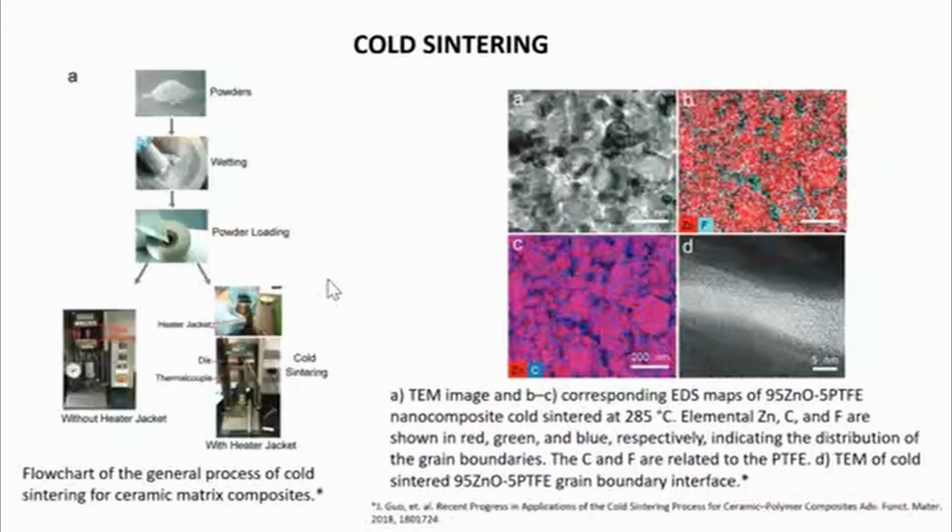Determination of a specific solvent is difficult, but can be guided through consideration of solubility data and phase diagrams. Kinetics can also be aided with the selection of particle size and particle size distribution of the ceramic phase. With multiple component ceramic compositions, binary, ternary, quaternary compounds, etc., we have to be concerned with the relative rates of each chemical constituent, as this can lead to nonstoichiometry.